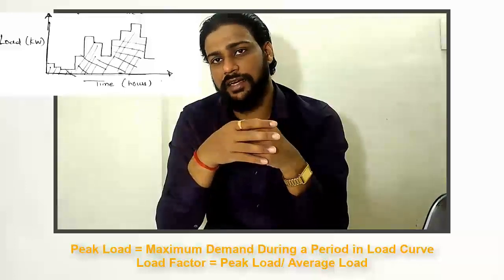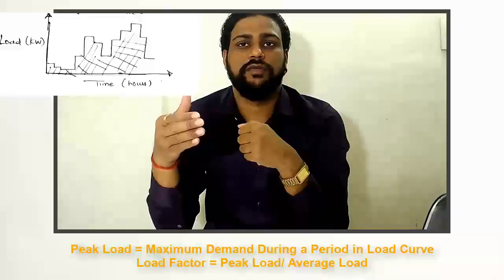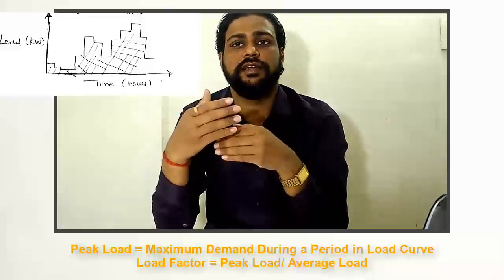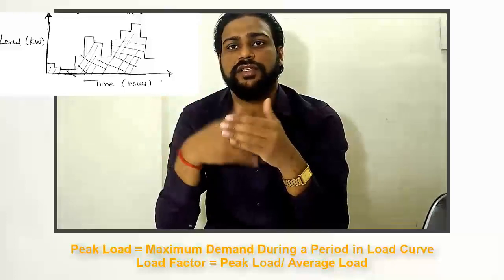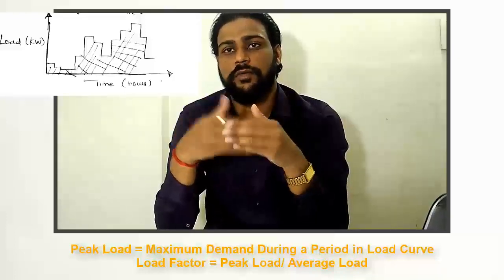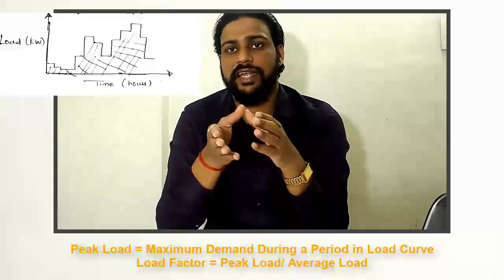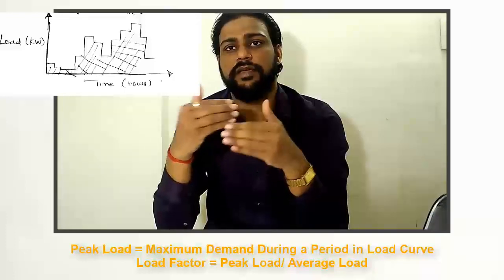So it will not be economical to run my power plant at 150 kilowatts for the full 24 hours. One of the reasons is that you can't store the electricity and it will get wasted, and there is no utilization happening. So the efficiency of your power plant and the plant operating factor will go down. So you need to have a standby generator or a standby power plant to supply that kind of peak load.